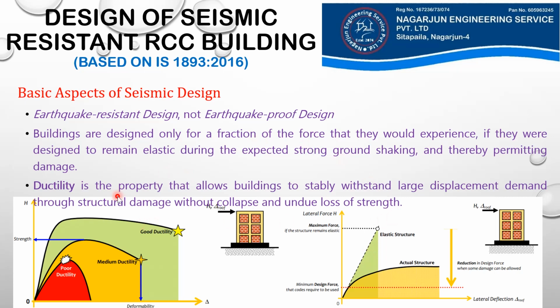So this is the basic concept in the design of any structure, any seismic design of any structure. That is, we won't be designing the structure for the full force that it may experience during the period of an earthquake, but we will reduce that force by using certain factors. And this is possible because we are allowing damage in the structure. We are not building an earthquake proof structure, but we are only building an earthquake resistant structure.